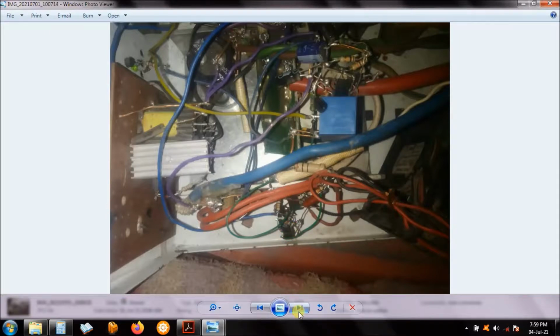Right, and then sorry, can go back. Here are the back current MOSFETs. They are here. This is the negative. Well, it's red. Sorry, I just use the wires that I have. Normally, when I build these things, I want to see if this thing is working, and I build it. I'm thinking about it. I just pick a wire and use it. It's red, but this is the negative, or the common negative, and this is the solar negative. They are switched here using MOSFETs.